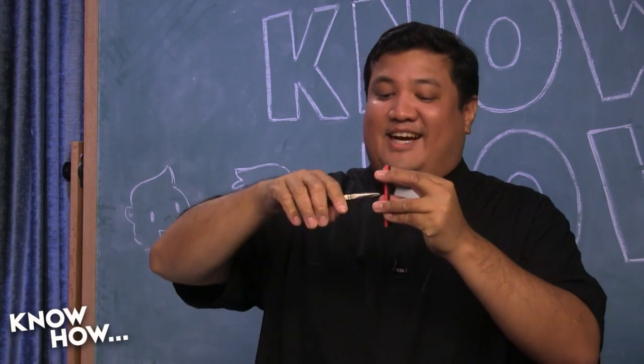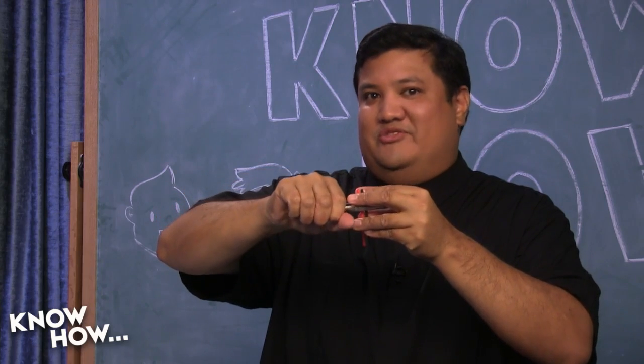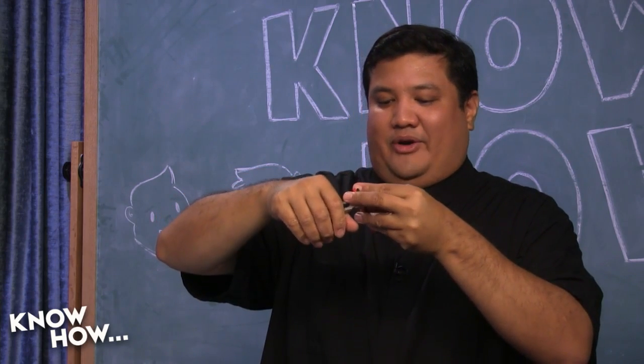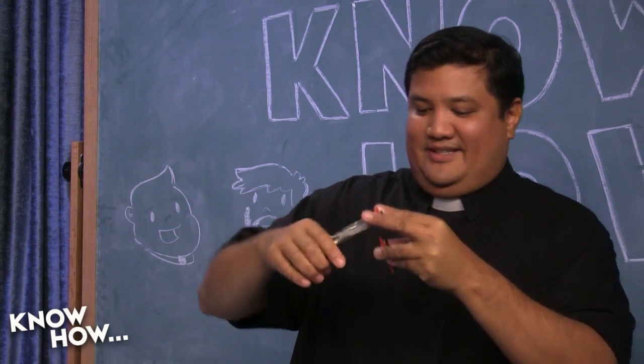Yeah, I've done that a few times. It sounds really stupid to say it, but everyone who's done this for a while has done that. You've soldered something together and then you remember to put the heat shrink tubing on. And what has happened to me too is I get this beautiful soldering job, the best I've ever done, and then I realize I have to rip it up. I have to cut it off, and when I redo it with the heat shrink, it's crummy.